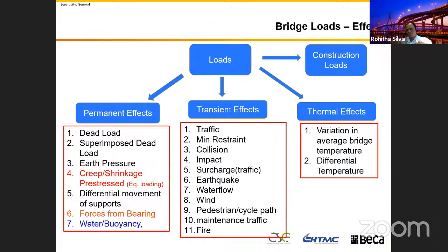For example, if the pre-stress or post-tension profile in the continuous span bridge is parabolic, when you put that parabolic shape along the bridge girder, that will produce what we call the equivalent load. Modern software will take that into account, but if you want to do a bit of hand calculation for your own satisfaction, it's better to understand that.